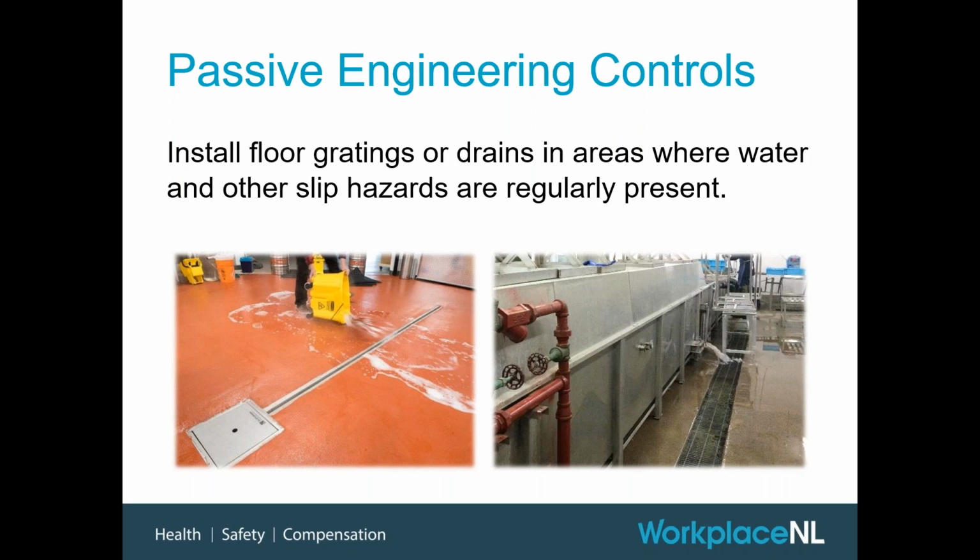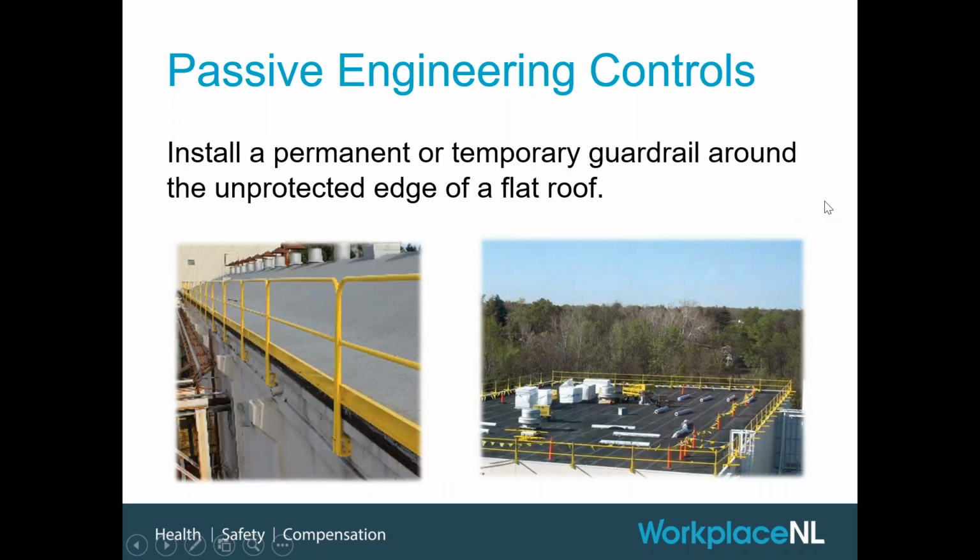So when you've got an area that leads into a workplace, often in the winter months, these places get full of water and ice and snow. Usually you'll just have a little mat or something there. But if you can add a drain, like a little trench or grading, it's a great way to help take care of the slip hazards that come from dragging in snow on your boots.